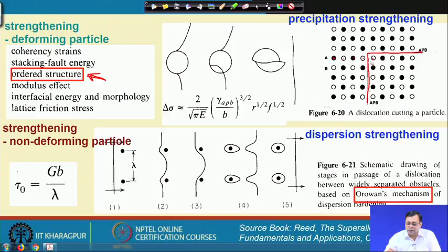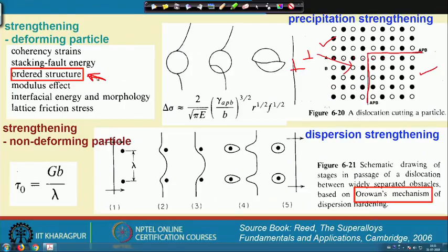So, this is a boundary between a phase and an antiphase. This antiphase boundary energy is important, because if one dislocation passes through this phase, then we need another dislocation in order to make the antiphase into the phase. This is the phenomenon of phase and antiphase in an ordered structure.